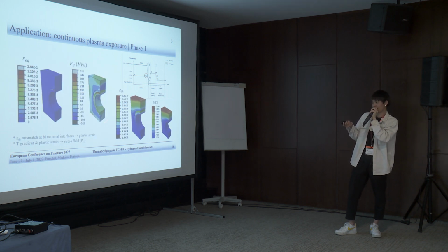We can see that a mismatch of thermal expansion at the material interfaces induced plasticity in the same zone. And due to the plastic strain and the temperature gradients, the hydrostatic stress field was like this.